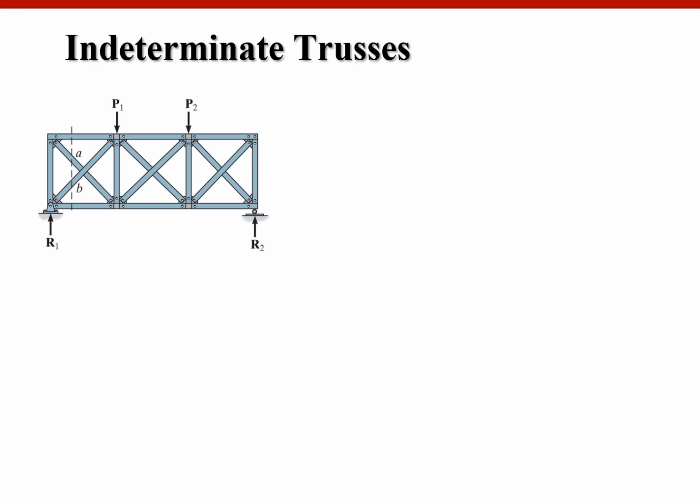How do I know this truss is indeterminate structure? Of course, you can use the determination equation, but simply when you have this crossover, if two members are crossing without node at that location, then the entire truss is already indeterminate truss.